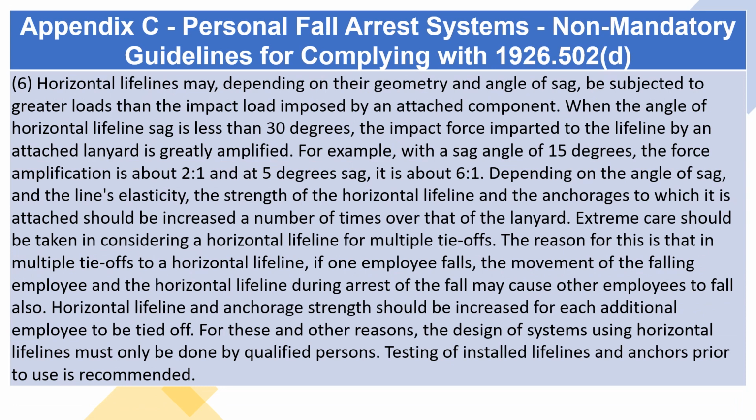6. Horizontal lifelines may, depending on their geometry and angle of sag, be subjected to greater loads than the impact load imposed by an attached component. When the angle of horizontal lifeline sag is less than 30 degrees, the impact force imparted to the lifeline by an attached lanyard is greatly amplified. For example, with a sag angle of 15 degrees, the force amplification is about 2:1, and at 5 degrees sag, it is about 6:1. Depending on the angle of sag and the line's elasticity, the strength of the horizontal lifeline and the anchorages to which it is attached should be increased a number of times over that of the lanyard.